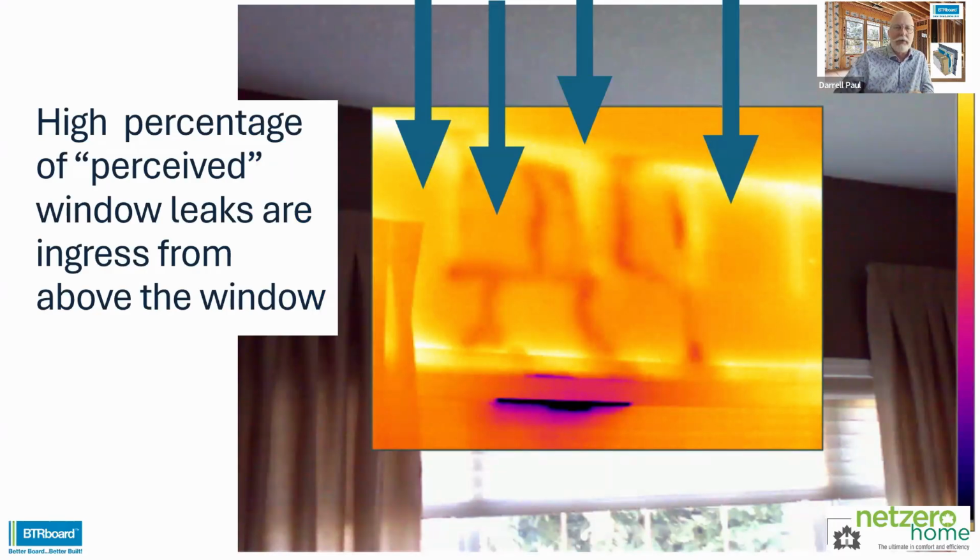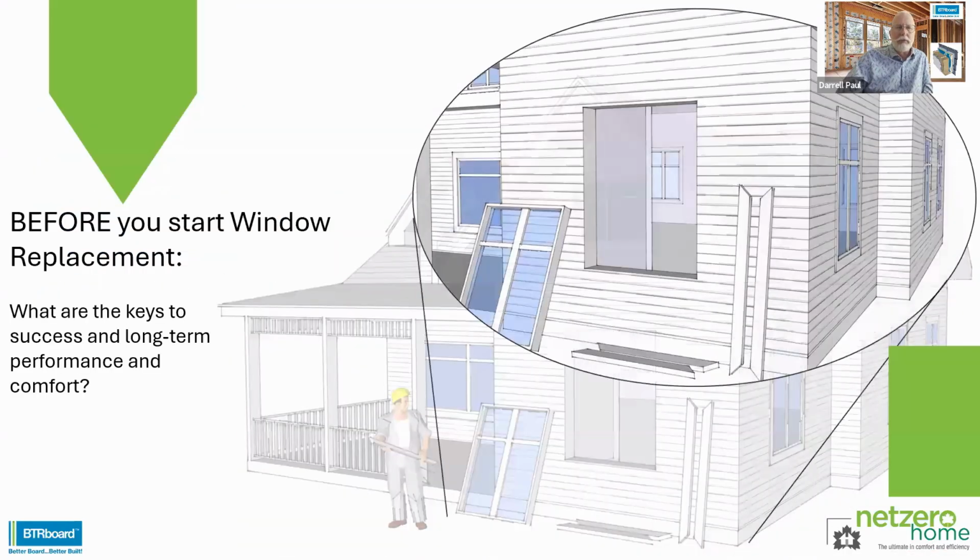And worse than that, when you think about adding insulation to the exterior, let's say you're putting a layer of continuous insulation or you're improving on the air tightness. Well, even in the summertime, when you would expect some drying potential to occur as the temperatures warm up and the humidity equalizes, you're not getting that because the wood is so saturated and soaking wet. For some of you who have taken buildings apart, you find that a lot of times the damage is irreversible. You have to go back in and do a lot of retrofit and replacement. So that takes us back to this statement here.